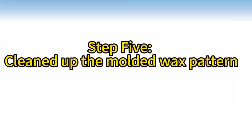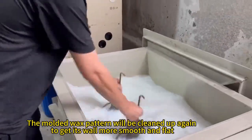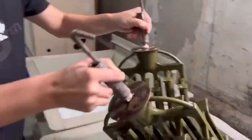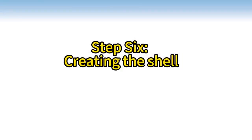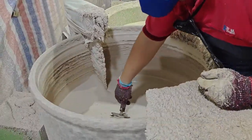Step 5. Clean up the molded wax pattern. The molded wax pattern will be cleaned up again to get its walls more smooth and flat. Step 6. Creating the shell. The wax tree is dipped into a ceramic bath or slurry.